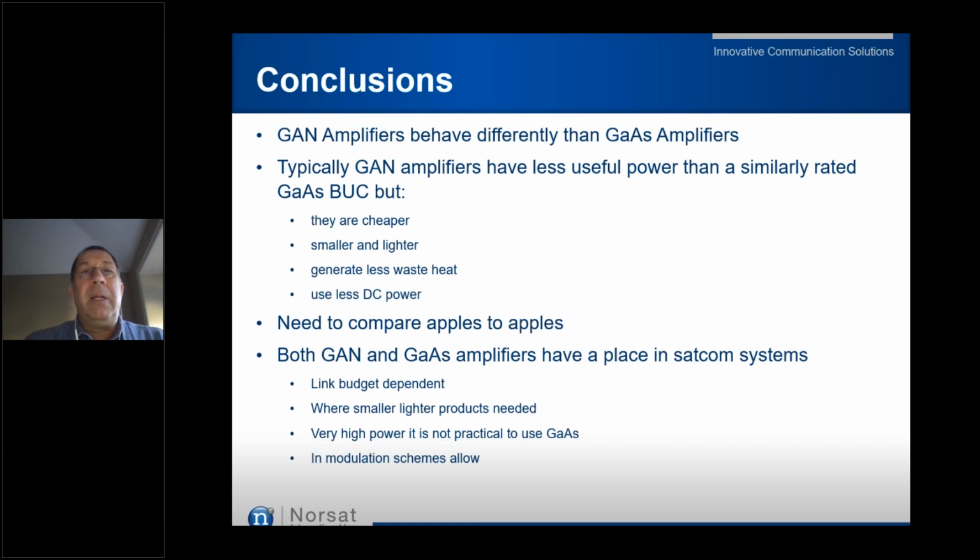And then any place where you have a constant power modulation scheme or a constant envelope modulation scheme, GaN products work probably really well because you can drive them above this nominal P-linear, and they don't necessarily cause any adverse effects because the modulation scheme is designed to be working closer to saturation.